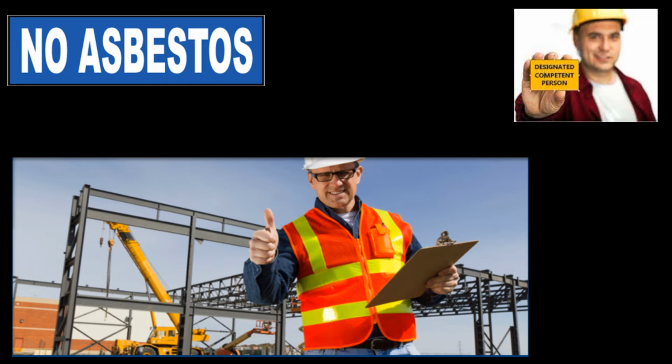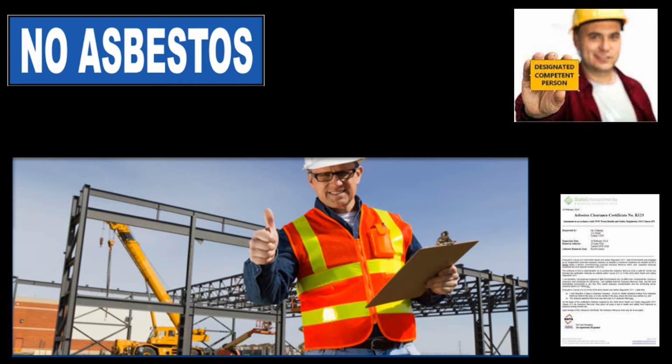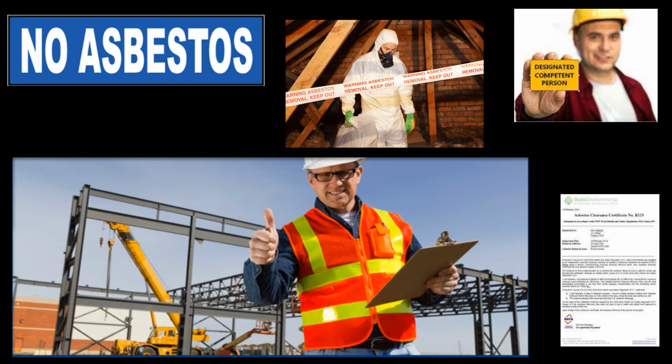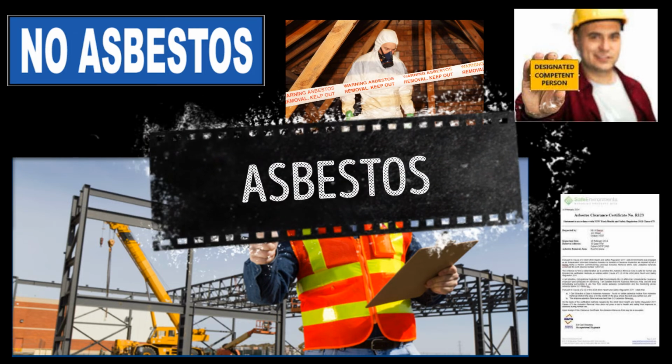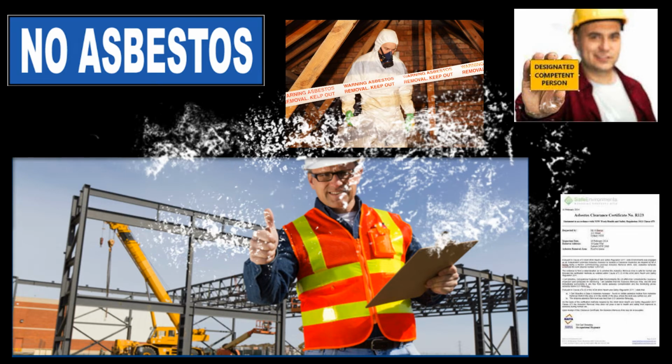Also, whenever they tell you that there's no asbestos, you have the right to see the asbestos clearing letter. There will be a letter of certification stating that the area is free of asbestos from a company that specializes in cleaning up asbestos. You have the right to see it before you go in the area. That is asbestos. If you have any questions, again, talk to the competent person for your company. And as the doctor says, next!